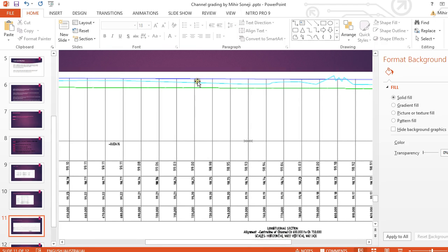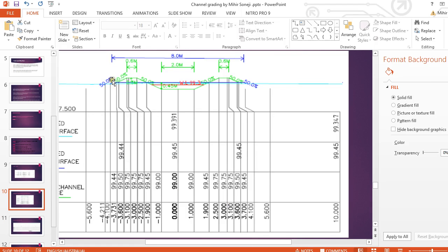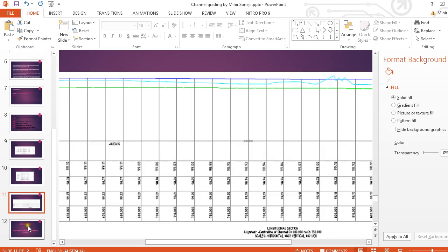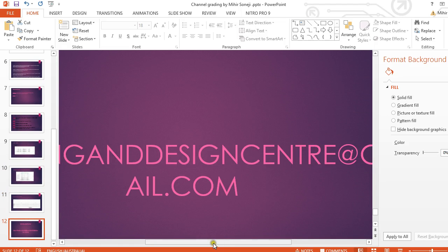I then created a compacted finish surface, which I call the pad surface in here, and then I dug down the channel and created a bank using Civil 3D. And then lastly, we're gonna measure the volume of earthwork.